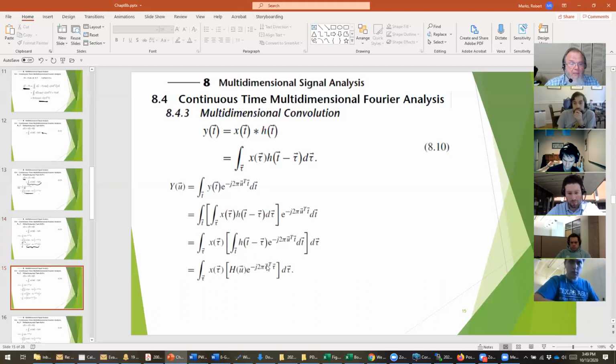So we get the original function down here, and all of the stuff in the square brackets just becomes the Fourier transform times e to the j shift, right? And now it's beautiful. We can take this transfer function outside the integral sign, because we're integrating with respect to tau, and that's not a function of tau, so we can take it outside the integral sign.